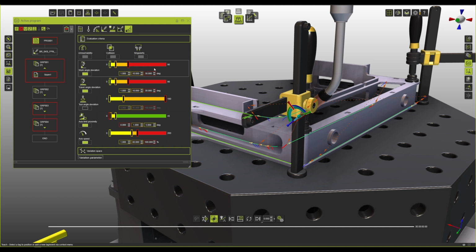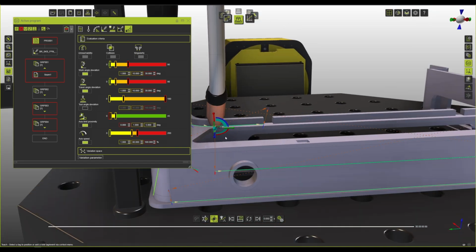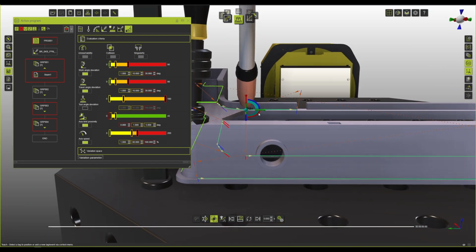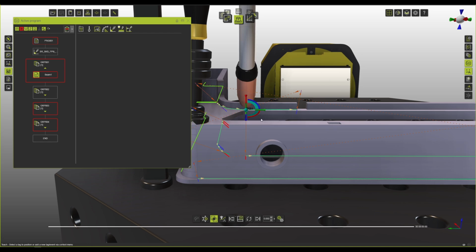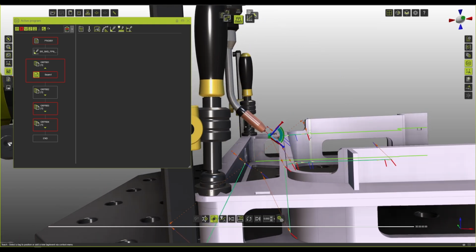The red section is anything above 30 degrees, which is not a solution. So anything you find above that is pretty much unusable. Something else needs to be done, and if you decide, you can abort the calculation. And these are the ranges that we have for the travel deviation. If you're familiar with this, you can see 1 to 10 for the travel angle, from push and pull, is reasonable. For the work angle, when you start getting out of this range, somewhere between 10 and 30, you're really degrading the quality of the weld, because you're eating too much into one plate. You might need a specific set of settings on the welder. You need to do some extra stuff. And above that, you're probably not even welding.